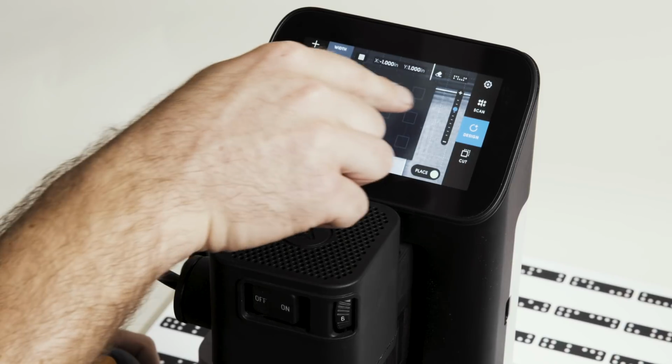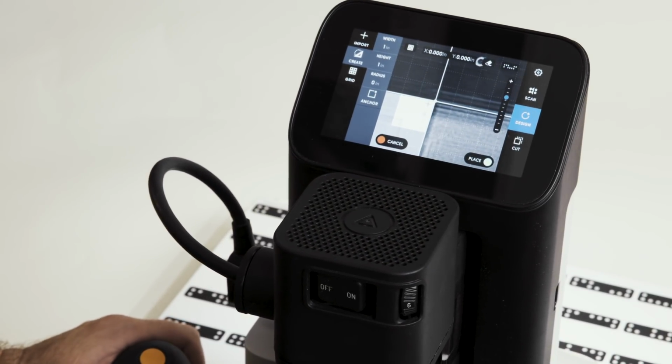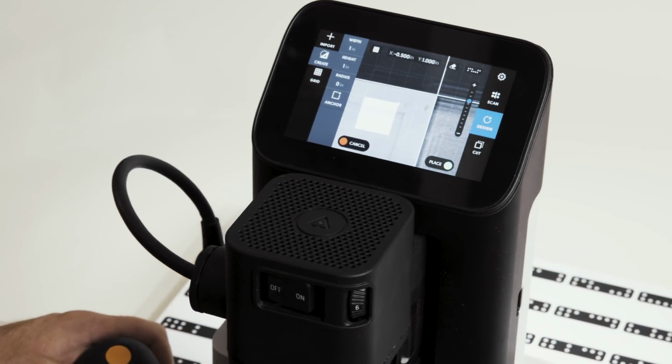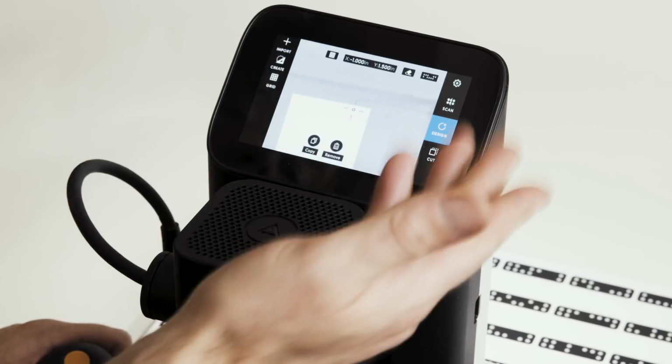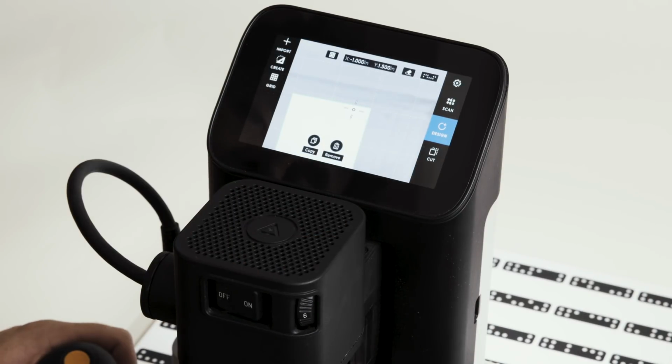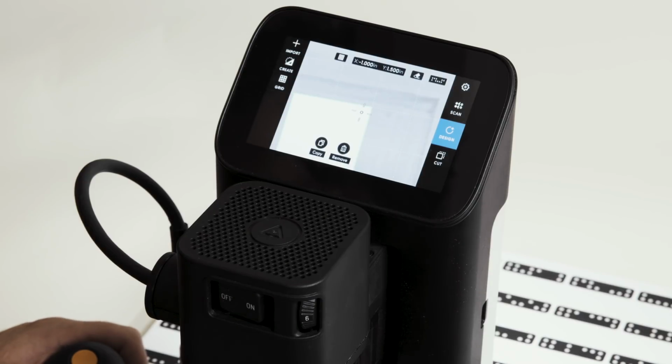I'm going to use the top right anchor point so that I can snap it to 0, 0 and know we're golden. Or snap it to any half-inch increment in this case. Or if I wanted to go in and modify my grid, I can use a different increment. So this identifies any 90-degree edge where we can physically probe the edges of the stock and places a grid very accurately aligned to that using the physical probing method.